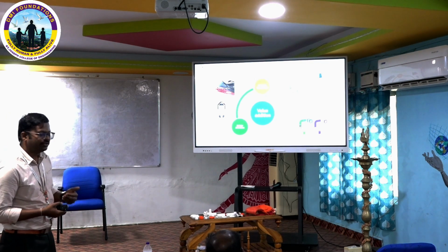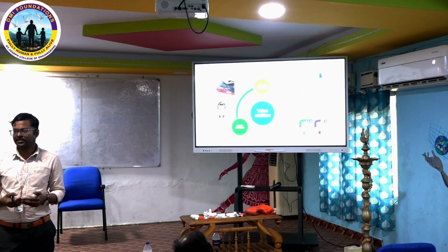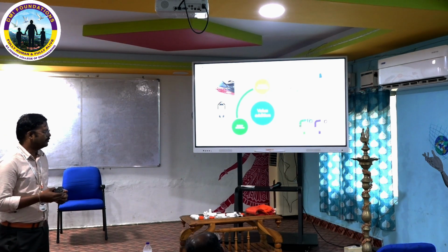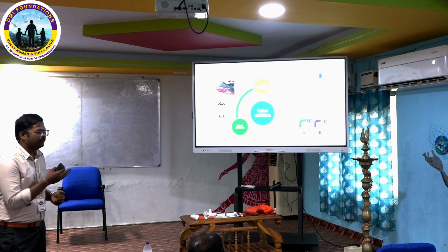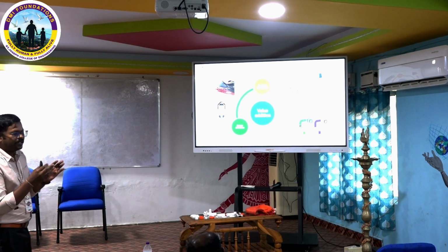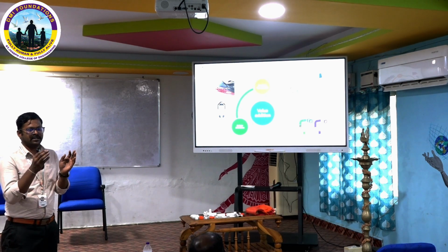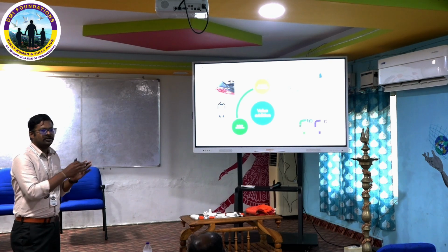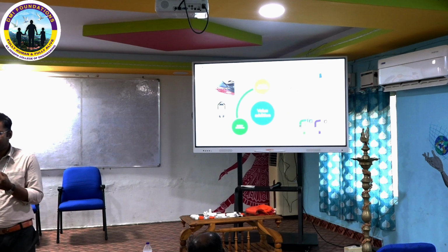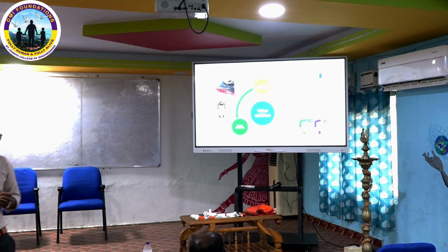So what will happen? It will reduce the fuel efficiency. So what did they do? They did topology optimization. In the fourth diagram you can see the optimized product. It only has material where the stress concentration is going to happen. With this they get material reduction and strength also. This is the main concept of topology optimization.